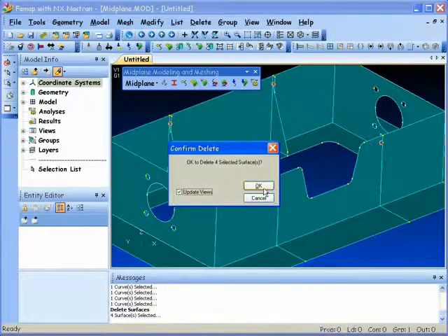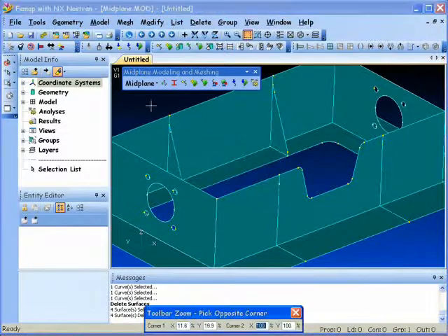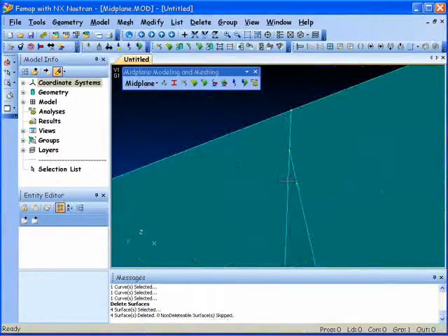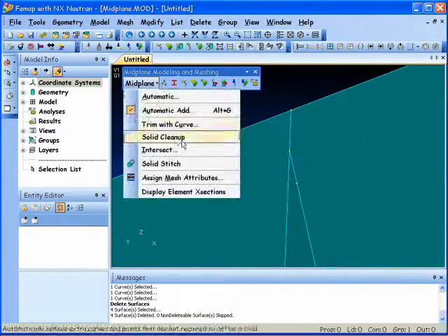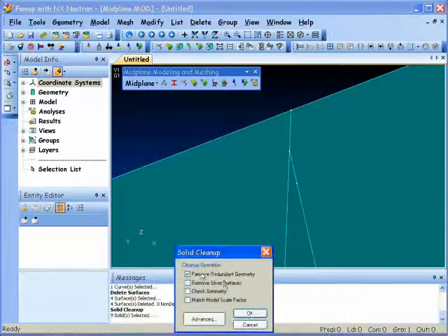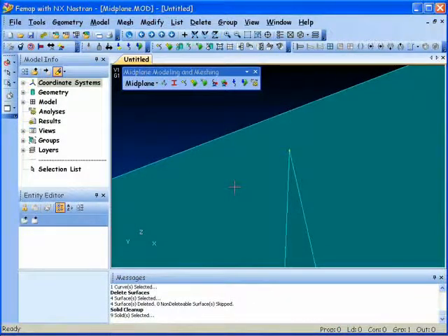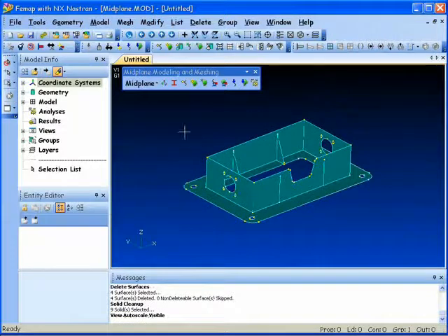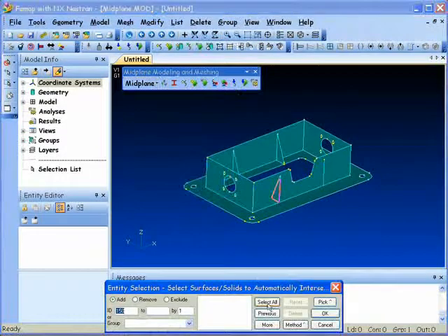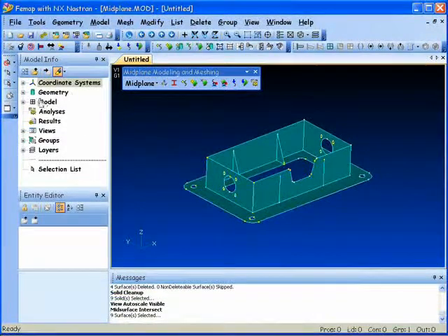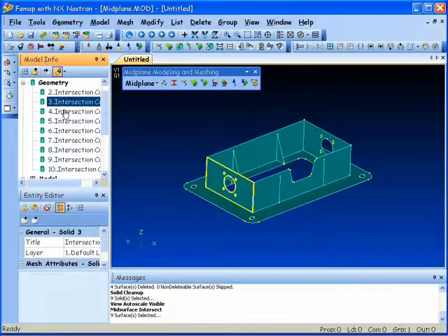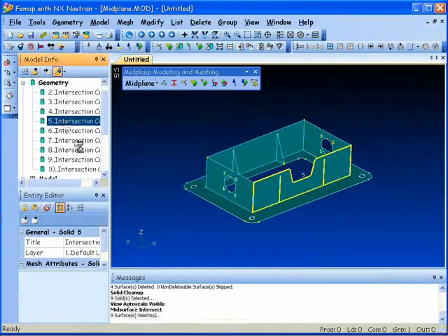And they're gone. If I zoom in on one of the ribs, you'll see that I've got a point at that intersection, where I did the trimming operation. So I'm going to clean that up with a solid cleanup command. And you can see that extraneous point is eliminated. Next step is going to be to intersect our surfaces. What this does is it actually goes in and creates intersection curves on the different walls. And you can see on the side wall where I've got alignment with the 2 ribs on there.